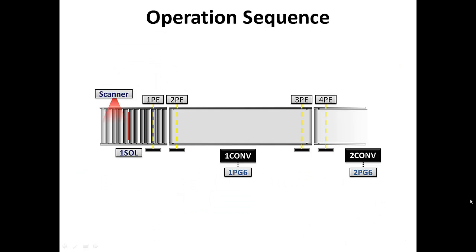Okay, let's take a look at this sequence of operation. We have a carton that comes out of the main production area. The scanner was good, it drops the stop and it sends it in. And as soon as the carton clears the second photo eye, meaning that it's all the way onto the buffer conveyor, then the system stops. Because remember, we want to accumulate at least 4 cartons on the middle conveyor, the buffer conveyor, before we take any off with a takeaway conveyor.